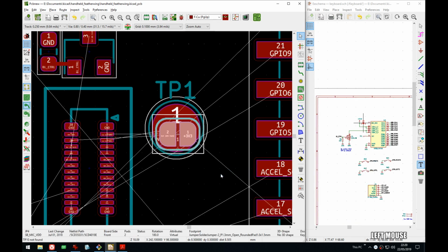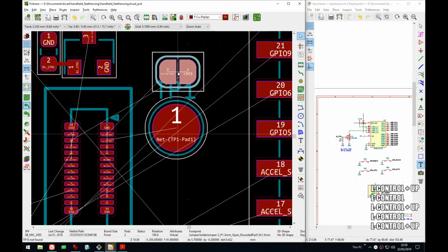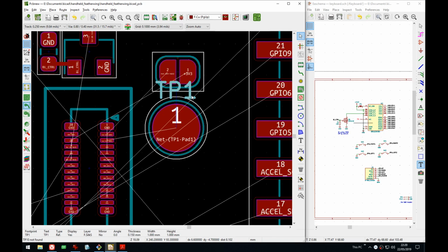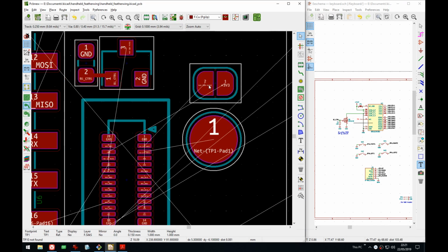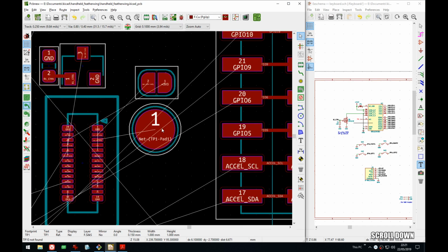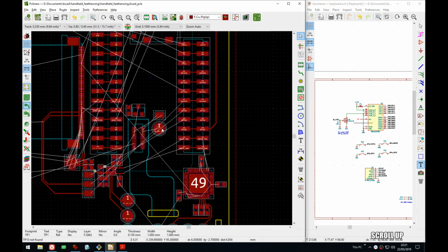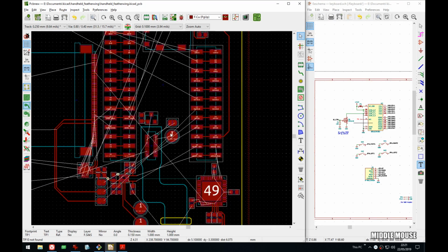So I'm gonna move this something like this. So you solder this to enable the mic, and then the mic output is here. You can solder a wire or something. The idea was that you could solder a wire back into the header, like into the analog in. I think these were analog out, analog in.